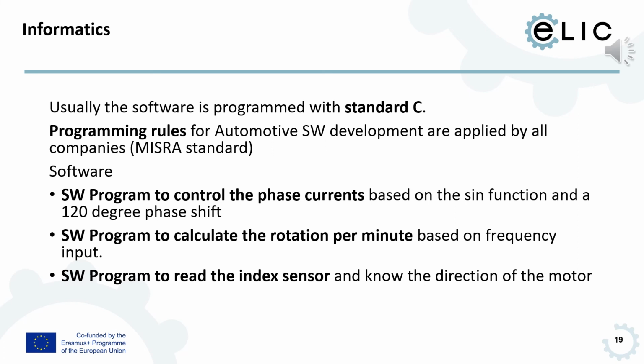And informatics is involved. Because when you look at this e-motor concept from outside, you would think, what is software doing? But software is actually running on the controller ECU. Without software, the motor wouldn't work, because the software is the algorithm that actuates the semiconductor elements to put the current on the coils and to coordinate them in the right sequence so that the rotor really is creating an RPM. Rotation per minute is RPM.